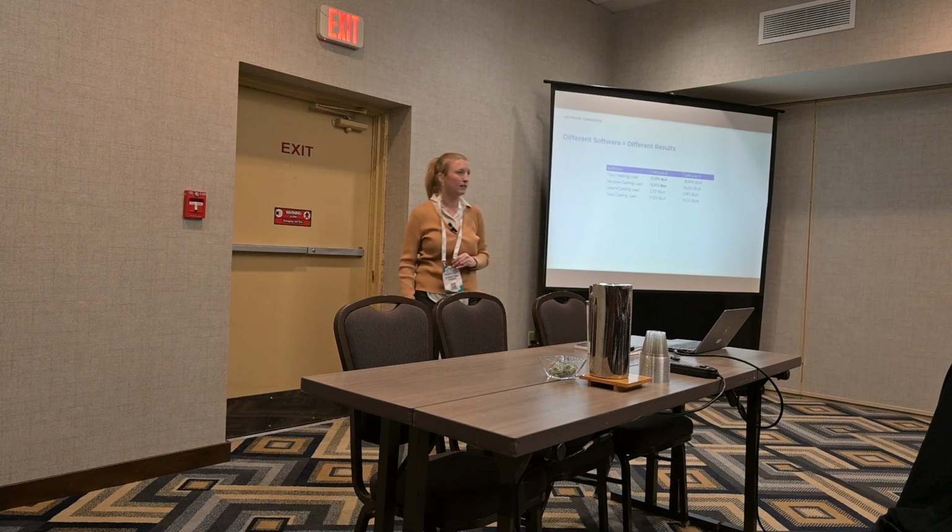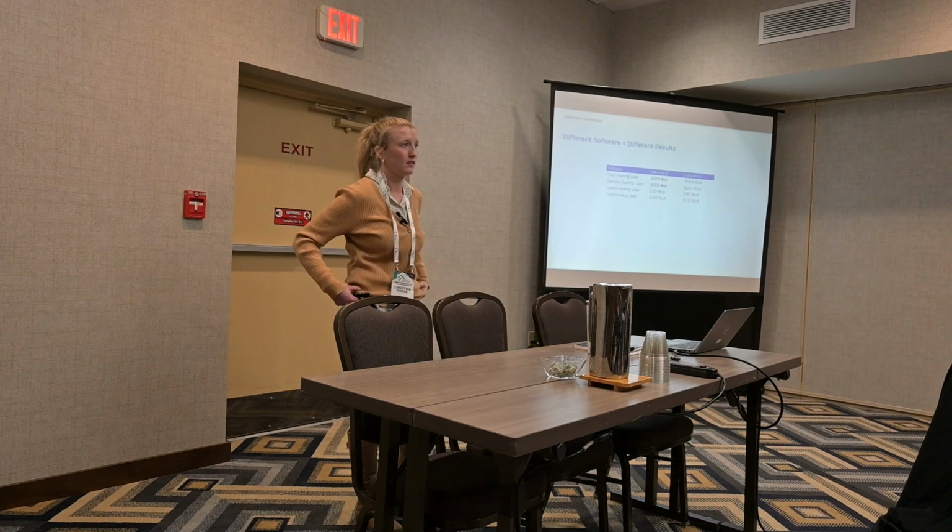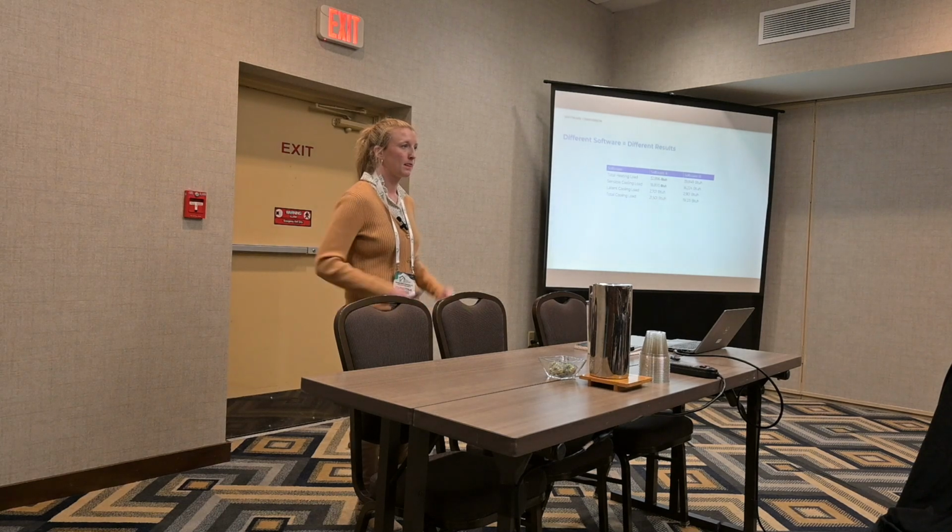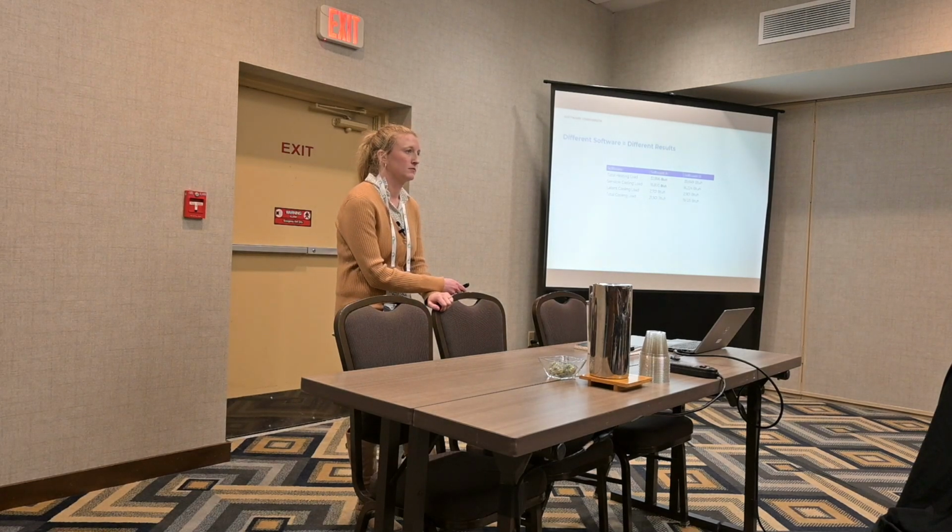Yeah, I was going to ask about this, so I'm really glad you guys got into it. I've noticed that default values for air sealing between different Manual J's can tend to be vastly different and come up with up to a ton difference in terms of sizing. But also manually entering it in, it just seems like some Manual J's will weigh air sealing a lot heavier than others, up to a whole ton worth of sizing. That throws me for a loop.